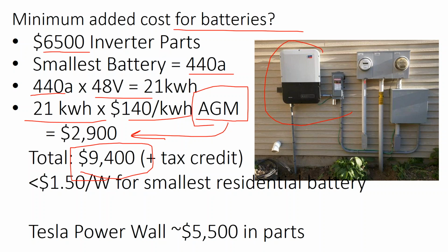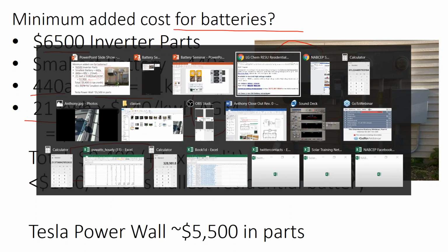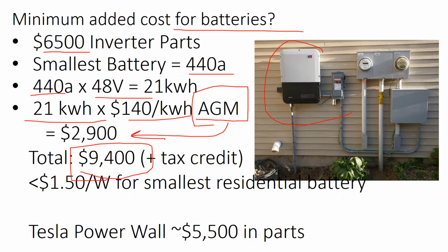Now that's where perhaps selecting, say, SolarEdge gives you a competitive advantage, because with the SolarEdge system, you've already bought the charge controllers. And so it's going to cost you a little bit less to upgrade with batteries on SolarEdge than it is with string inverters. That's why I'm waiting with bated breath for string level optimizers, kind of like what Pika is doing, because that'll take the increased cost of the SolarEdge system and drop it down a little bit.